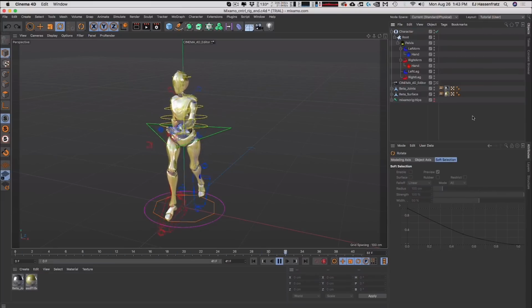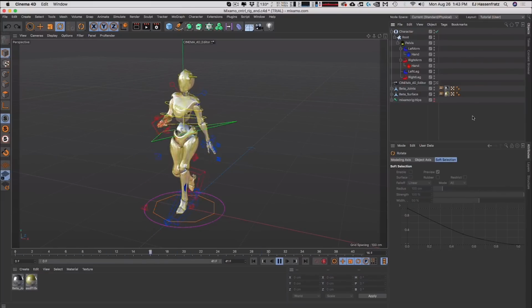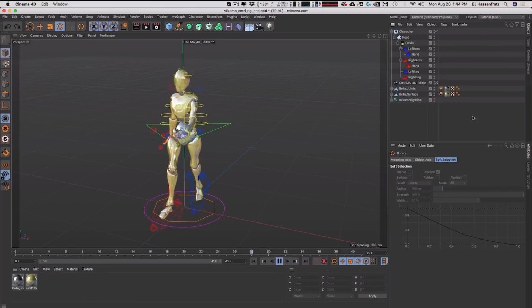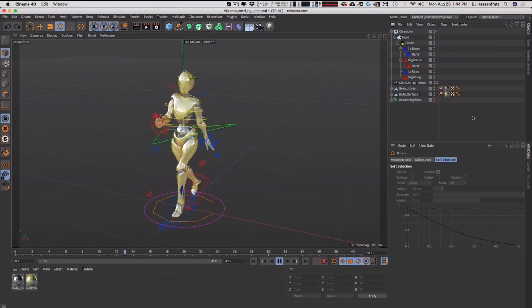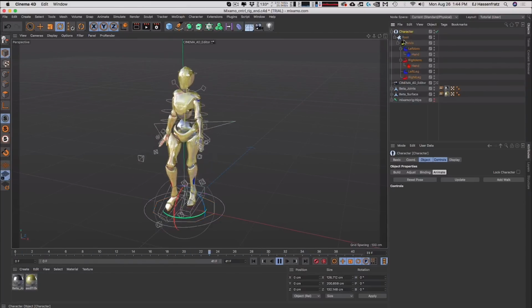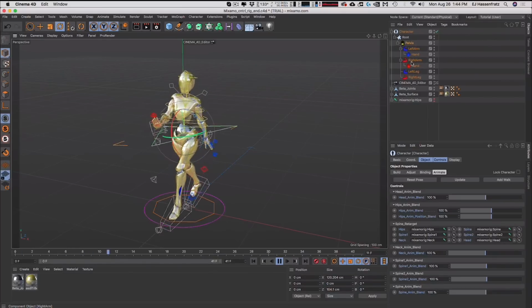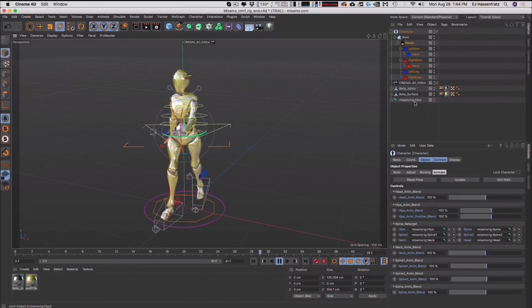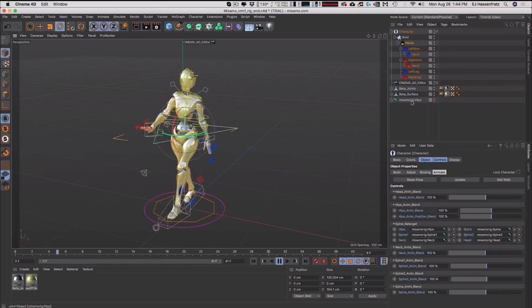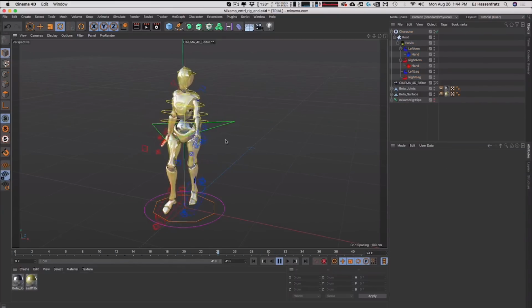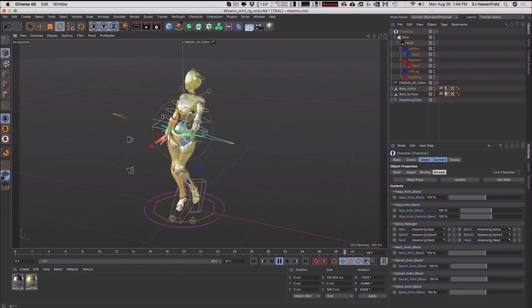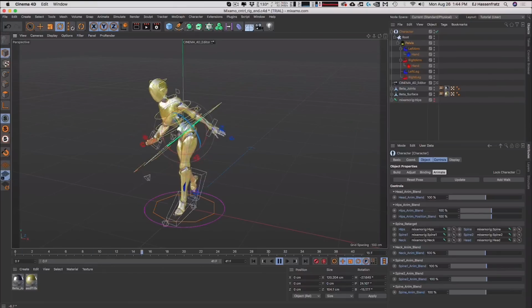Now, if you are a character animator or anyone who uses Mixamo and brings in that Mixamo mocap animation and applies it to any characters in Cinema 4D, R21 has a great new feature called the Mixamo control rig. And what it actually does is allows you to use this Mixamo control rig that's built into the character object and allows you to set up that character object to link to your Mixamo mocap rig, and you're able to adjust and animate on top of your Mixamo control rig.